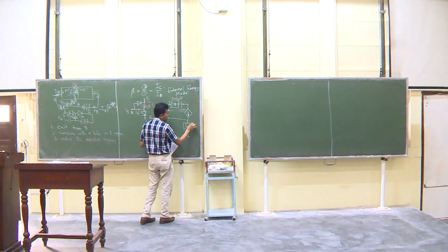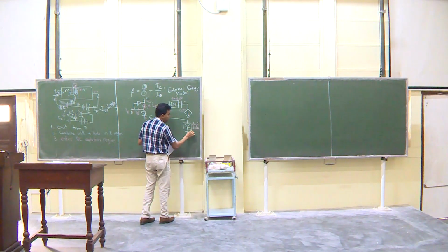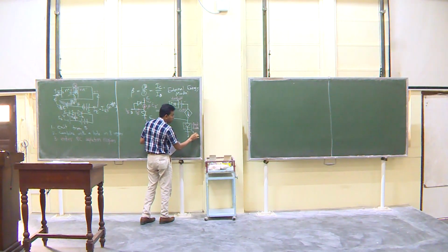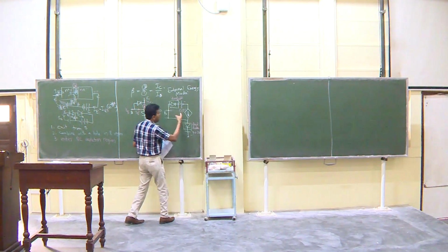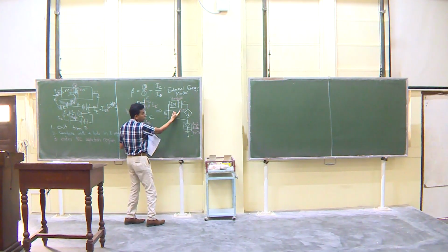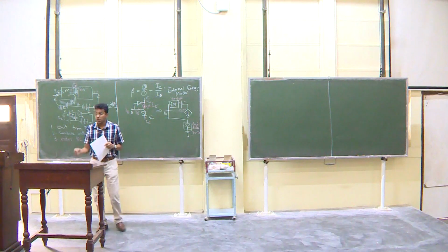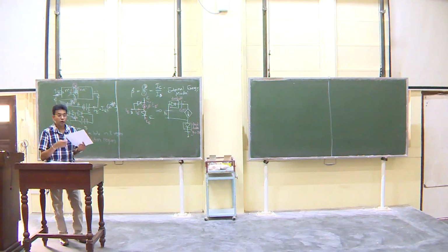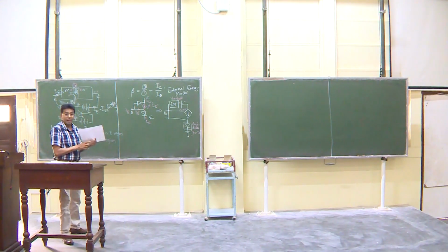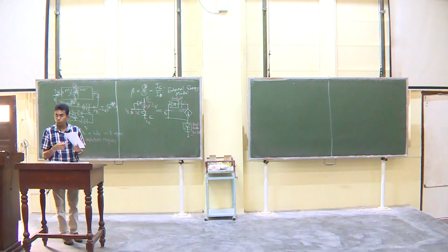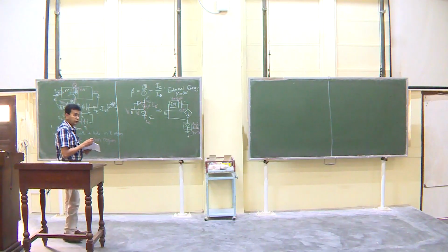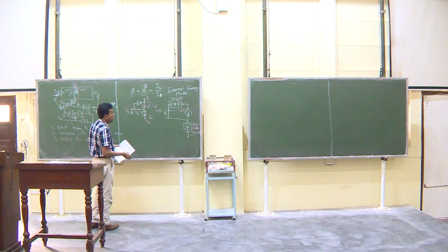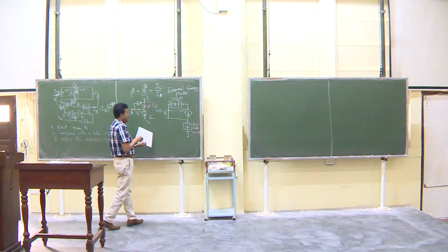This is again an ideal diode with this being 0.7 volts. Note the difference, this is 0.5, this is 0.7. Okay. Why? The 2 junctions are not equally doped, they have different dopings. So, therefore, different forward drops.